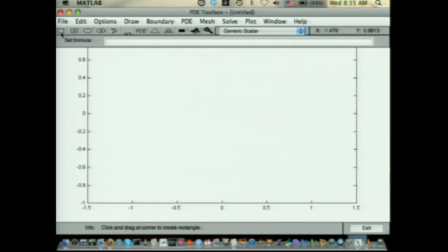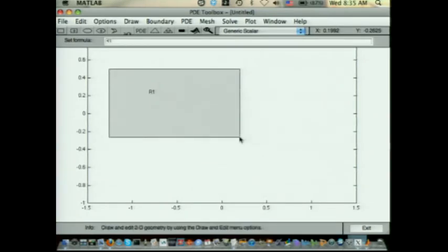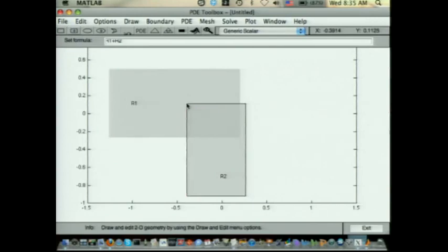There's something. All right. So first, let's start off with a rectangle. And look, it gives me a little plus sign when I push the button. It's because I can draw a rectangle. Woo! R1, which means rectangle 1. By the way, what happens if I do the plus? That means wherever I start from, I build my rectangle. So wherever I put that plus, that's where the rectangle starts. It goes outwards. Before, wherever I put it, that was one corner to another corner. So it's a corner start or a center start on your rectangle. There's 2 rectangles.